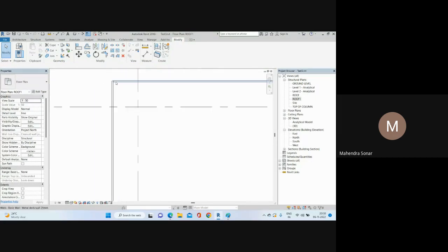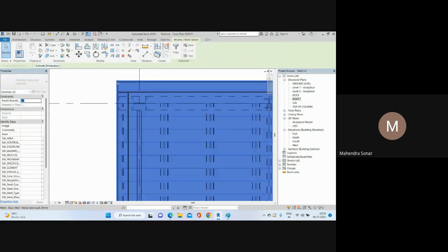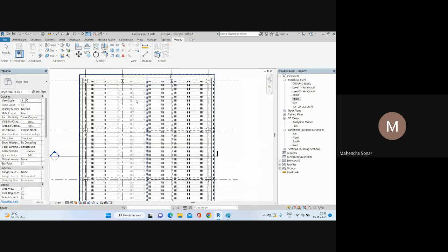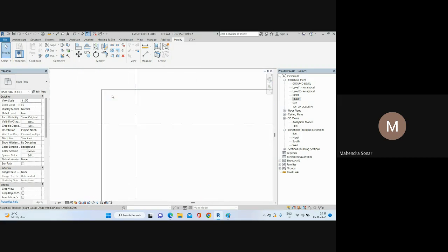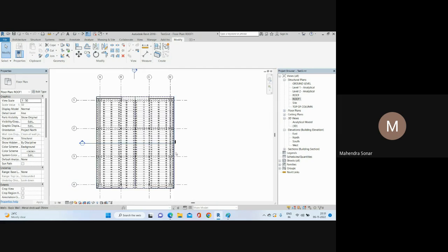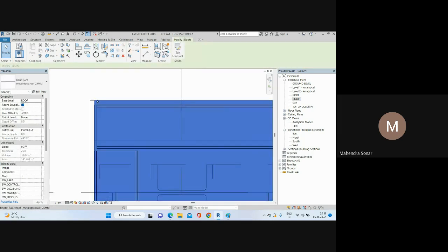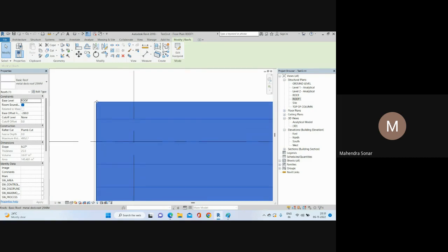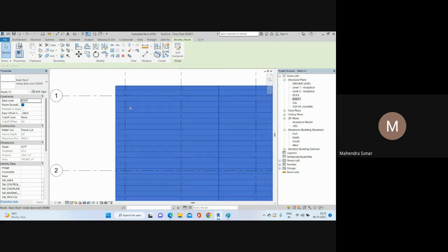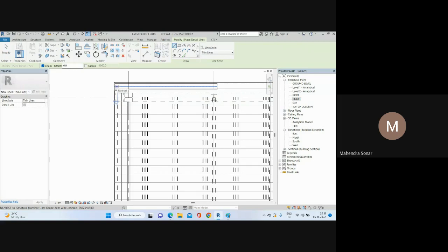So what we'll do, first of all those lines for the wall, side guards and roof we need to hide. Okay, so you can just hide. Before hiding this roof, if I select, oops, where is roof? Okay, so you can see this is the corner of the roof. Before hiding this roof, you need to add the line work for the boundary of the roof. So we can just give the dl command. Dl means detail line, simple line.